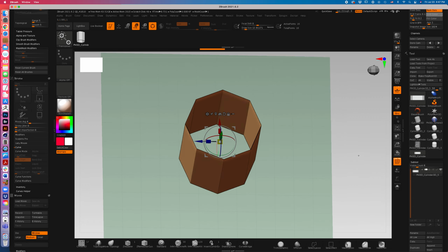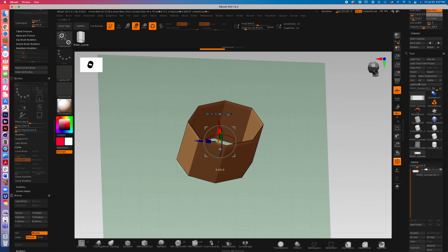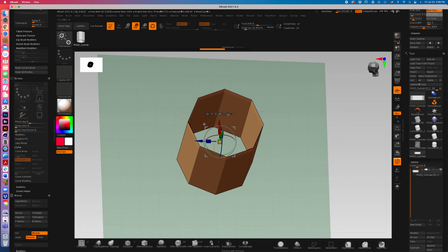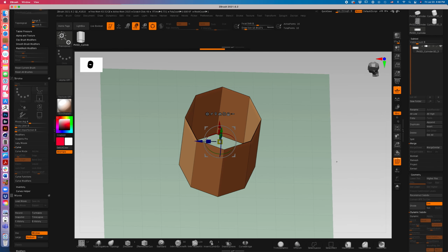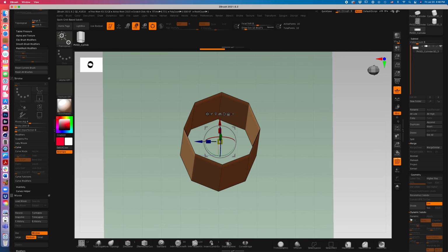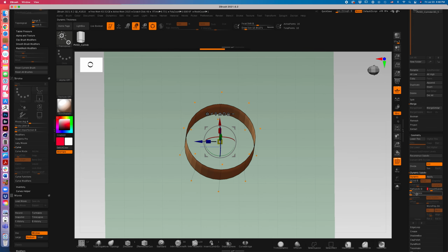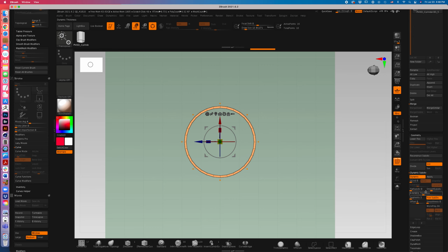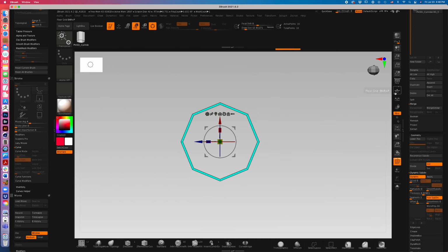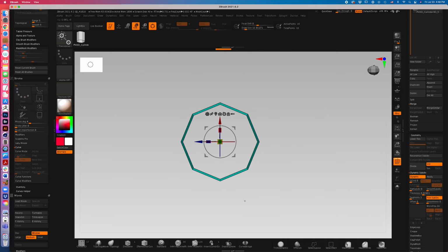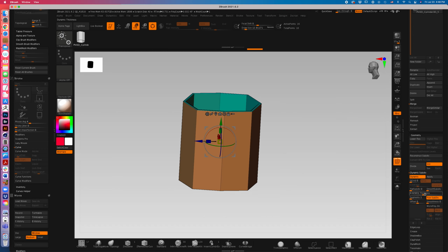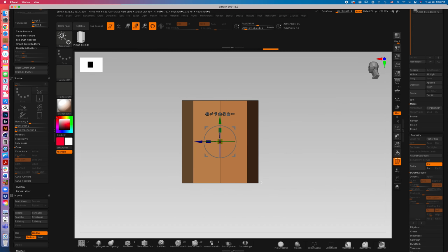The trick is that I want it flattened a little bit this way. I could do it without looking at it from the end, but I really like to look at things from the end when I'm doing that. The problem is when you look at it from the end, you can't see it. So if you go under Dynamic Subdivision, turn smoothing off and turn thickness up like this, what you'll get is there's still just one polygon. It has no thickness; Dynamic Subdivision is giving a little artificial thickness. I'm just going to select or mask everything except those center polygons and bring them together like that. We can then turn Dynamic off and look at this from this way.